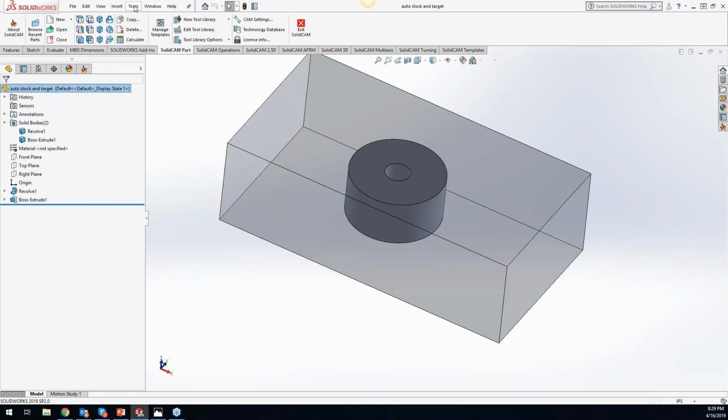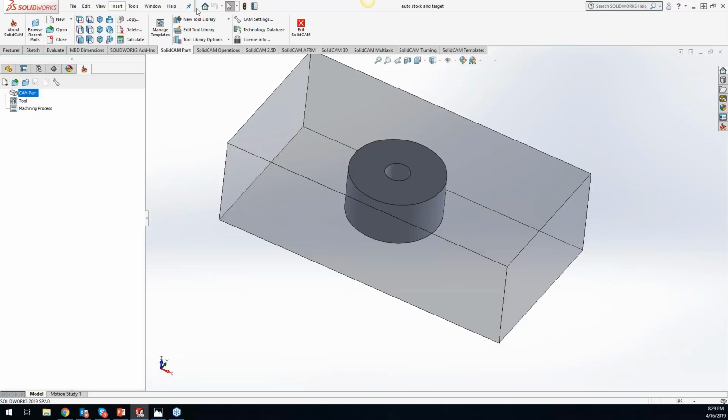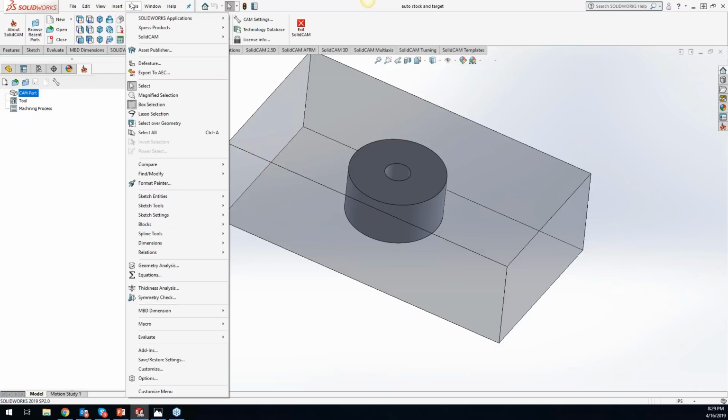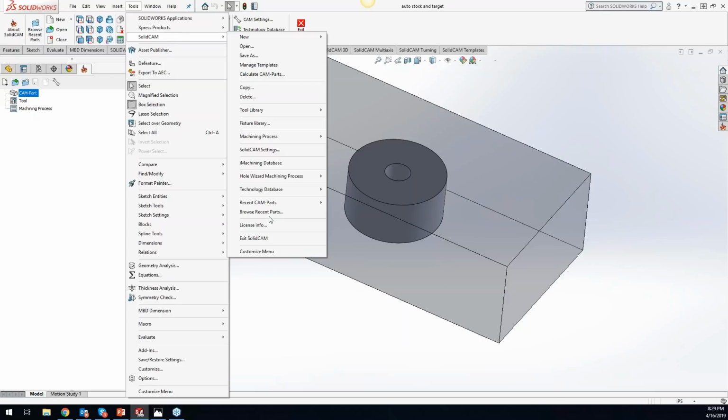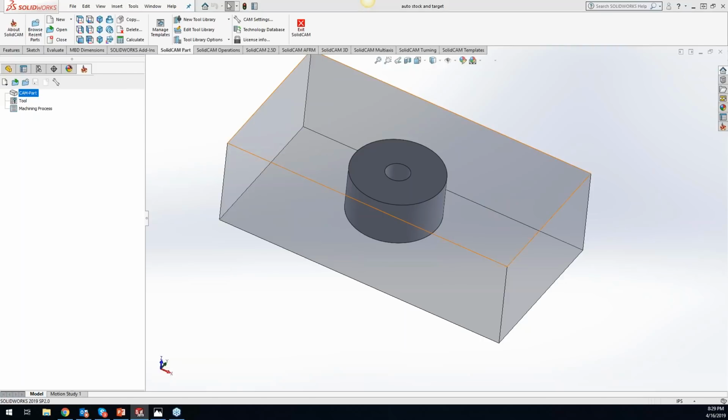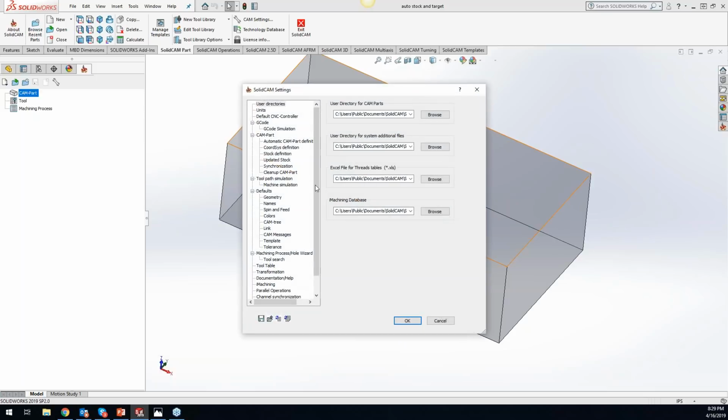Let's see, where was I going now? Like I said, I can't remember if this is something new that they added in there for 19, but I came across it and I wanted to share it with you guys. After you create a coordinate system, you'll notice that you have to accept the levels, and then it goes to the coordinate system manager, and you have to hit the green check mark out again to get out of there.